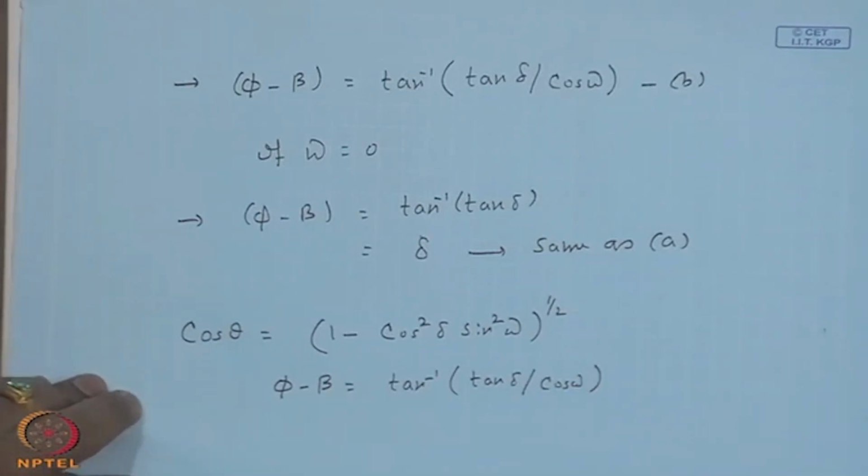So, you adjust beta with the time of the day as given by this expression, and then you will have the angle of incidence being minimum for this mode of tracking, where an aperture plane with a horizontal east-west axis is rotated about the east-west axis.